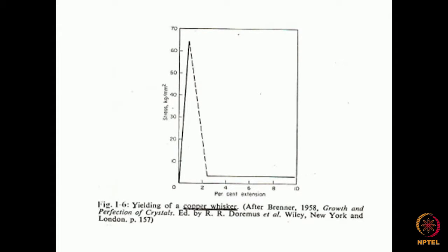And you know that the other question which comes is that the line defects, when we talk about them, are they equilibrium defects? They are not. Okay, that we will come to later. But can we have materials which don't contain any dislocations? Yes, it is possible. This we call whiskers. Small dimension samples which can be produced without any dislocations, but point defects will always be there in the material.